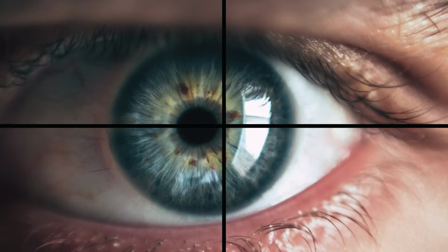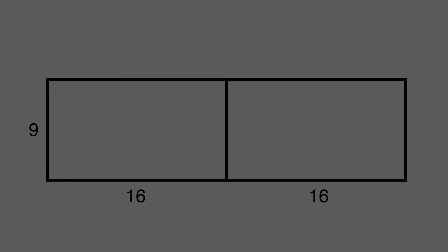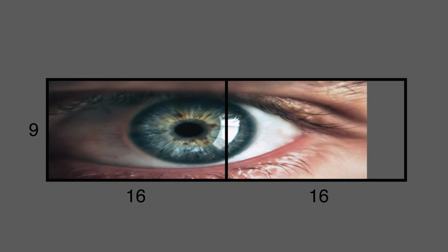These inexpensive video wall controllers don't change their input resolution as the resolution and aspect ratio of their effective output changes. The computer sees the device as 4K 16:9, aka the conventional aspect ratio for 4K display. And that works fine if you've got 4 TVs connected in a 2x2 grid. It works if you've got 9 TVs connected in a 3x3 grid. We've still got a 16:9 aspect ratio. But if we connect 2 displays horizontally side by side, the video wall controller is going to stretch the 16:9 image across a 32:9 space.